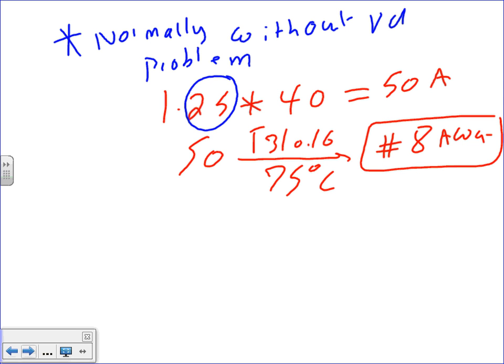Two things left in this chapter. We'll talk about them next time. Number one is voltage drop. We're going to size for the fire pump voltage drop. We'll do the same calculation, guys, except for the locked rotor current. Locked rotor current is a fancy name for the starting current. Voltage drop based on locked rotor current is very easy.